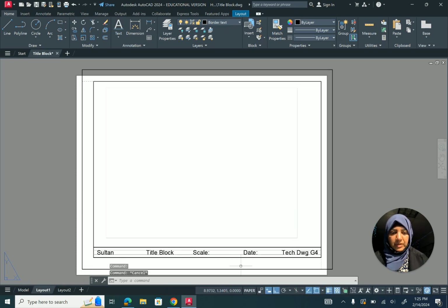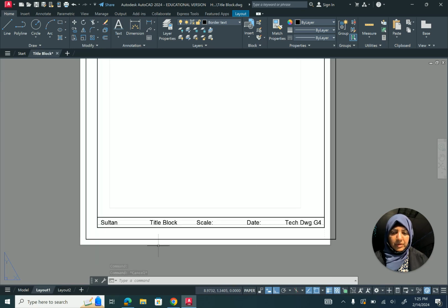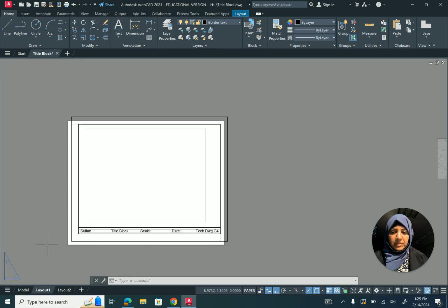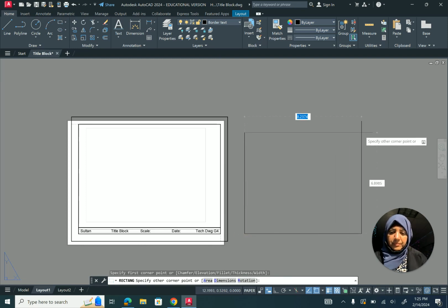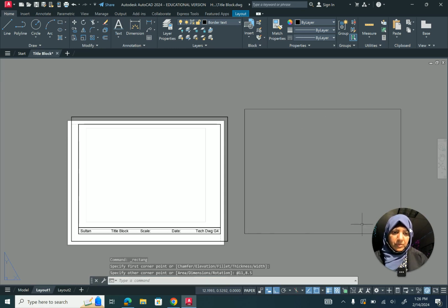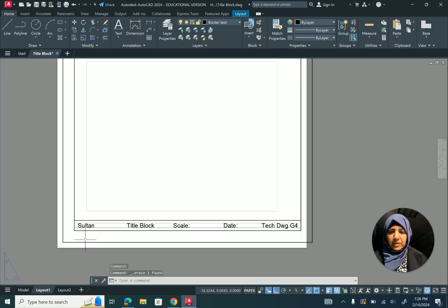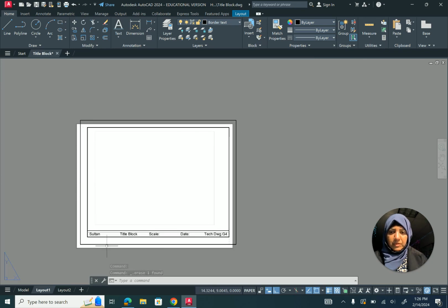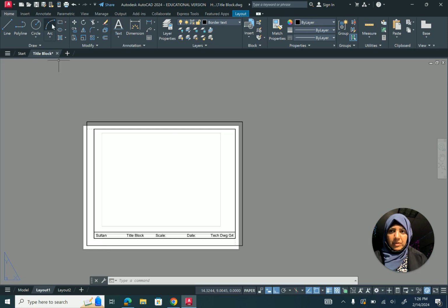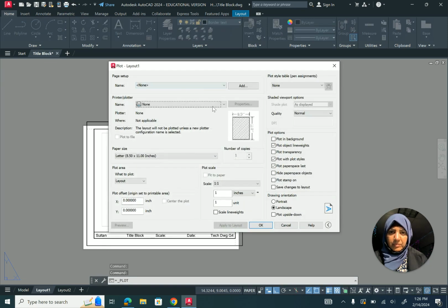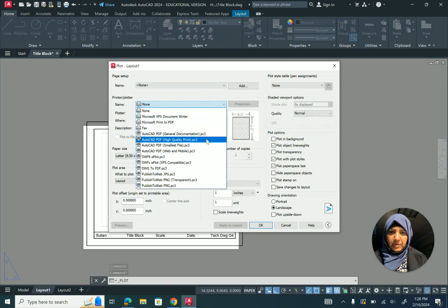So now this layout is for 8.5 by 11 or 11 by 8.5. Whenever we talk about giving dimensions for a rectangle, so for example, I draw a rectangle of this, that's going to be first the horizontal dimension 11, comma 8.5. So first horizontal and then vertical. And delete this. So now as you can see, the white paper is shifted, the drawing is shifted off of the white paper. So we're going to fix that by assigning it a layout.